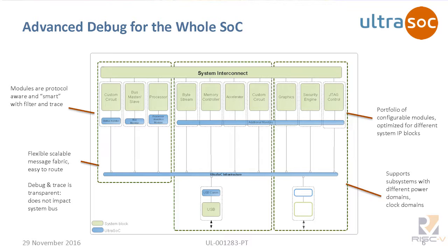And so what we provide, UltraSoC that is, we provide 3 classes of IP. The first class is a bunch of analytics modules. The first obvious one is the run control for a processor. This is your classic breakpoint setting, starting, stopping, going, looking at debug state of a processor. Then we have a bunch of others, and the more complex and more important ones are things like the